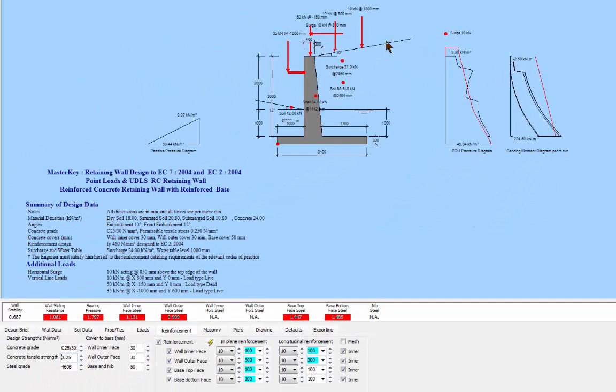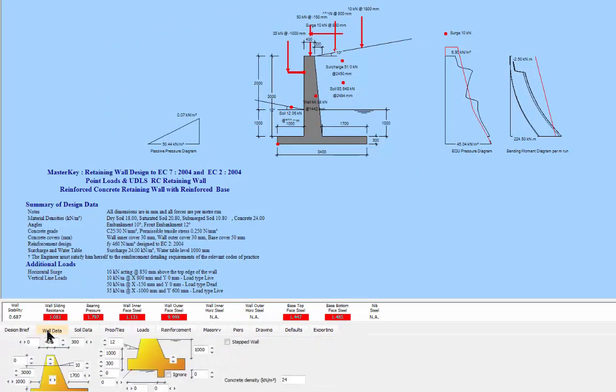We've obviously put in an additional load from a sloping soil. That's very straightforward. We can have the soil at 10 degrees here, and we've even sloped the passive soil at 12 degrees. So here's the passive soil coming in at 12 degrees. We've also then got a water table, and we've moved that water table up to 1 meter above the base. To me, that's a good belt and braces, because even though it's going to be excavated and refilled and drained, I always like to leave a bit of water. But if you don't want to, you just pull that right down.